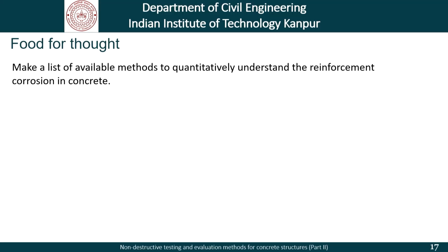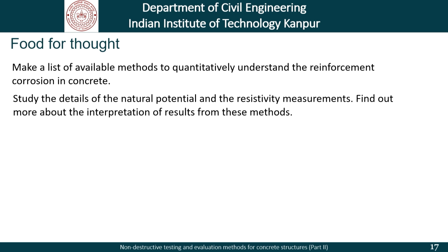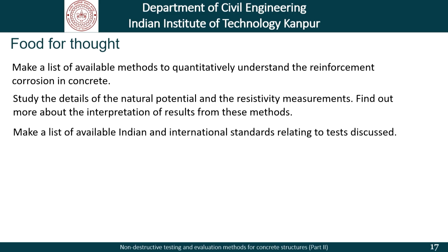Make a list of available methods to quantitatively understand the reinforcement corrosion in concrete. Study the details of the natural potential and resistivity measurements. Find out more about the specific interpretation in terms of results from these methods. Make a list of available Indian and international standards relating to the test discussed, not necessarily only the natural potentials, but also perhaps Schmidt-Hammer, ultrasonic pulse velocity, and so on.